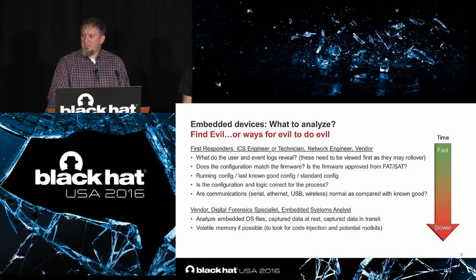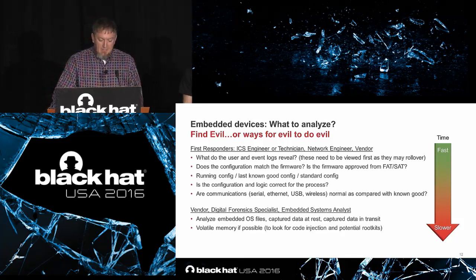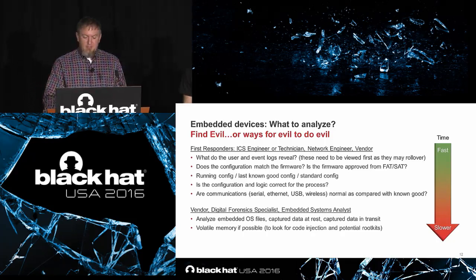And newer devices, they have more storage, so that may not be a problem. But again, a lot of these control system devices are out there 15, 20 years. Does the configuration match the firmware? Is the firmware approved from the factory acceptance test? Is it running a standard configuration that you're normally used to seeing? With the Aurora attack at INL, they changed the settings in the relays. And if they would have pulled the configurations from those relays, they would have noticed something was different.